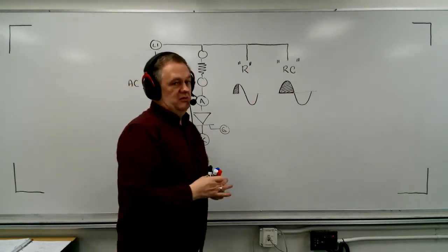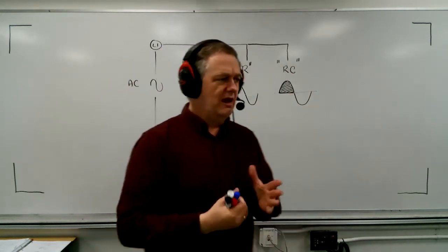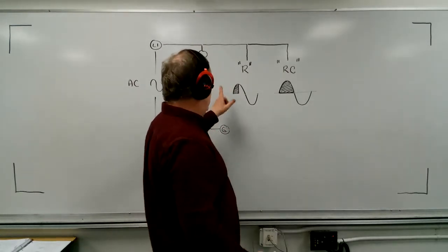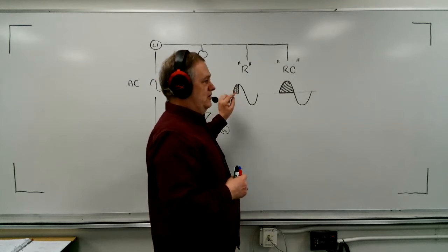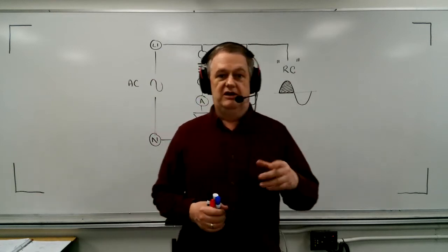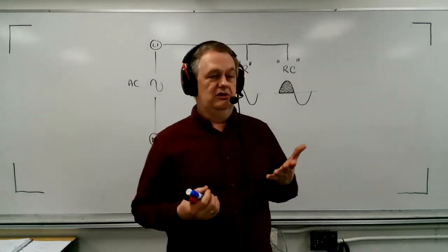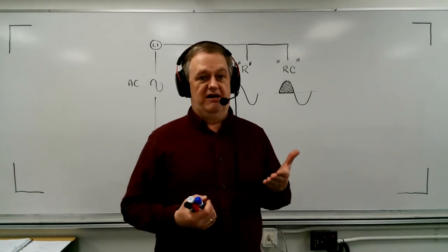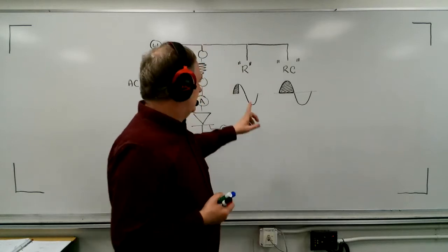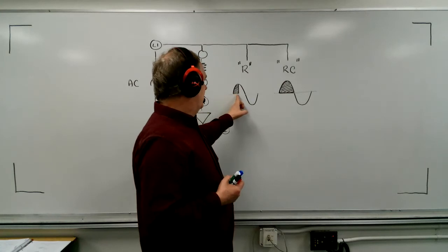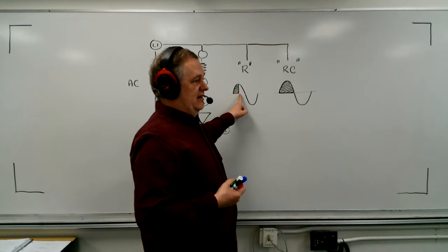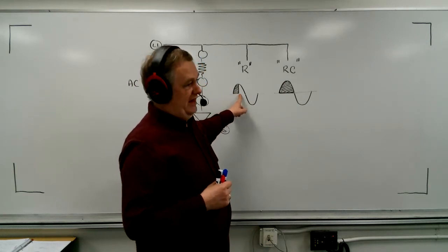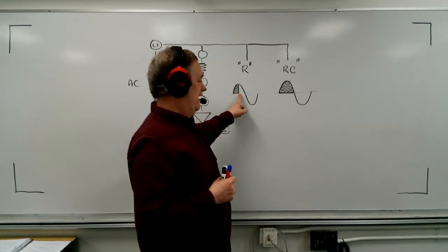What would have happened before is, if you turned the circuit on and started at 0 degrees, your load voltage would have started at the value of your line voltage times 0.45. And as your triggering circuit got later and later, up to 90 degrees, you would have E line times 0.225, which is half of the 0.45.